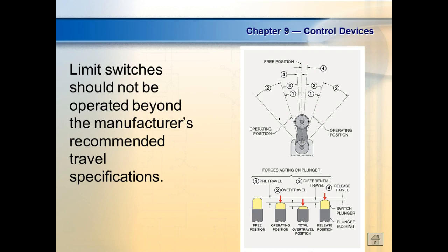Limit switches should not be operated beyond the manufacturer's recommended travel specification. We just talked about that. So what would you do if you operated beyond its travel specification? You're going to damage it, no doubt about it. You're either going to strip it out, right? You understand? Or you're going to break your operator, or you're going to bend everything up inside of it.